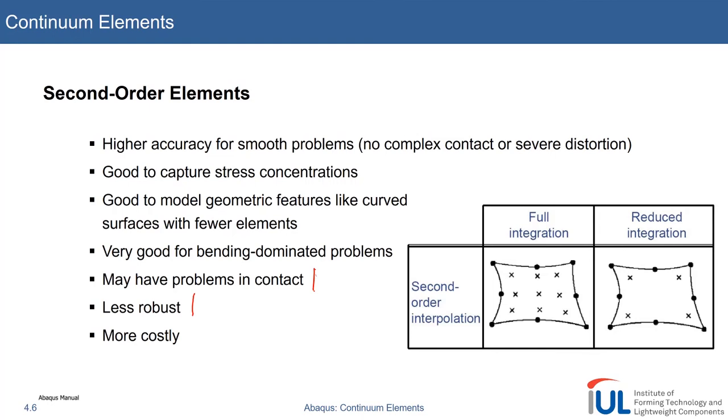However, I hope by the end of this tutorial you will also get a feeling for when to not just increase the number of elements by 5, but rather do smart modeling, because even nowadays, smart modeling and an educated mesh generation can help you save a lot of time or even give you better, more accurate results. So much for the interpolation.